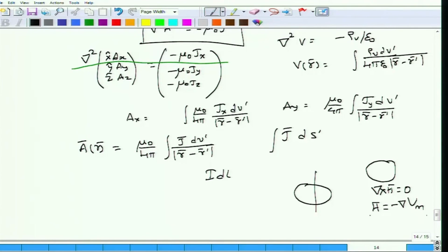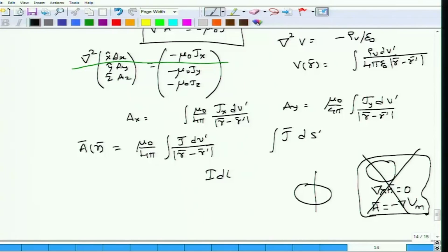You can do this, but the magnetic scalar potential is not very useful except in very special cases. So we will not be introducing the scalar potential for magnetostatic fields. In any case, the magnetostatic scalar potential is multi-valued, and dealing with that when the path encloses current is not possible. So for this reason we are not introducing the magnetostatic scalar potential, although the textbook for this course talks about it. This is not really important as well.